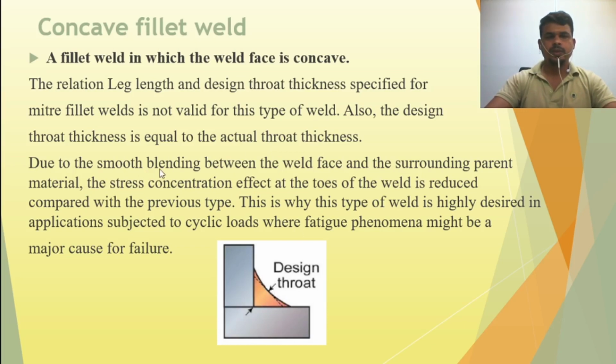Due to the smooth blending between the weld face and the surrounding parent material, the stress concentration effect at the toe of the weld is reduced compared with the previous type. So this is why this type of weld is highly desired in applications subjected to cyclic loading, where fatigue phenomena might be a major cause for failure.